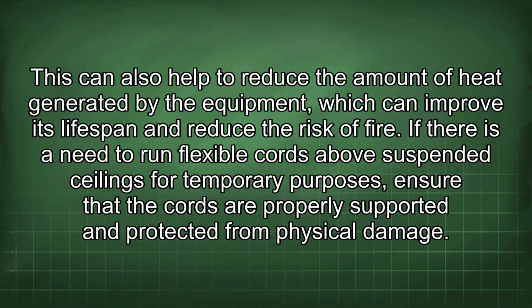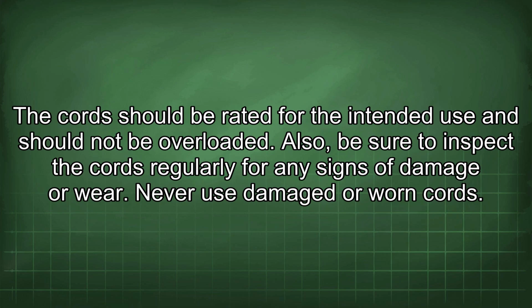If there is a need to run flexible cords above suspended ceilings for temporary purposes, ensure that the cords are properly supported and protected from physical damage. The cords should be rated for the intended use and should not be overloaded. Also, be sure to inspect the cords regularly for any signs of damage or wear. Never use damaged or worn cords.